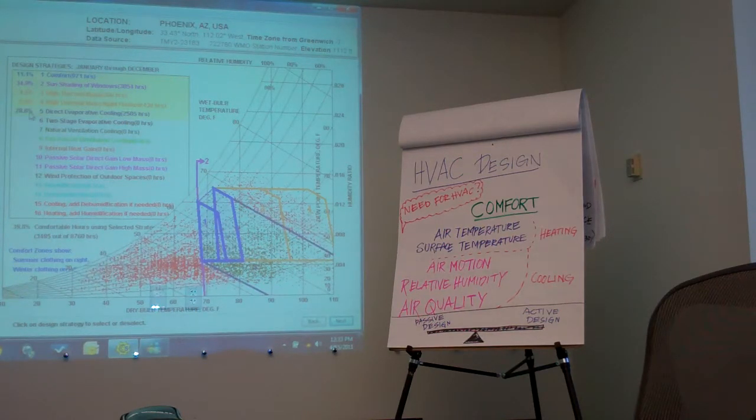But look at this, direct evaporative cooling. But we have the problem with evaporative cooling. What is that? Add moisture. Right. If we add moisture, then what's our problem? Fungus and other problems, right? Okay. Two-stage evaporative cooling has a little bit more than direct evaporative cooling because you're not directly exposing or adding moisture to it.